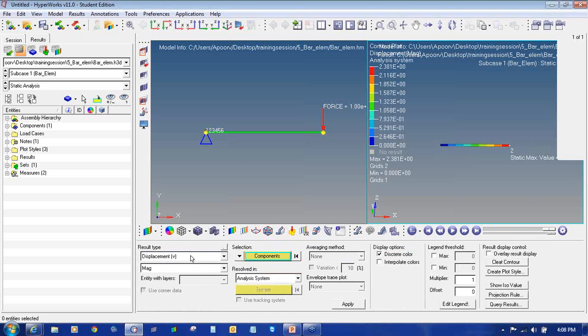And the value of stresses, if I click on the contour plot, you can see here C bar, C beam, longitudinal stress, SAC, SAT, SAE and SAF. So if I pick on the C point, it will show me the stresses as 300. If I pick the D point, it will show me the 0 stresses as it is a neutral axis. At E point, it will show me again the negative, that is compressive stresses. At F, it will show me again 0 stresses. So now you can see these results.